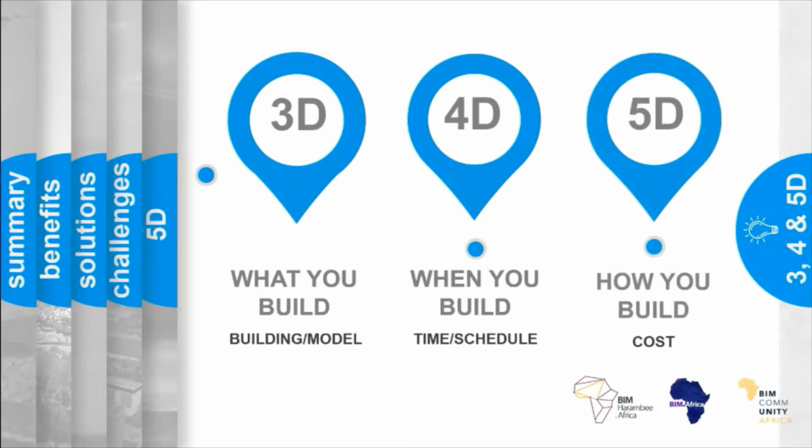To start, we've got to understand where it comes from. So 3D and 4D, we know the first three dimensions being height, width, depth, are physical measurable dimensions representing objects, and multiple objects in a construction model or in a building represent what we intend to build. When we then look at the fourth dimension, which was known to be time, and we apply time to each of those objects, we can get the construction schedule or construction program, which represents the sequence and the order in which we intend to build that structure.